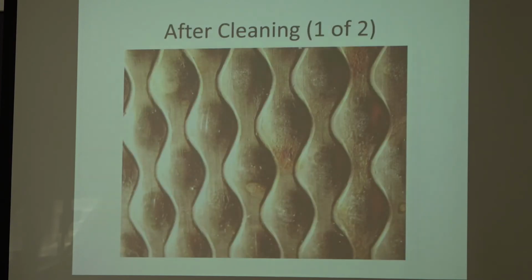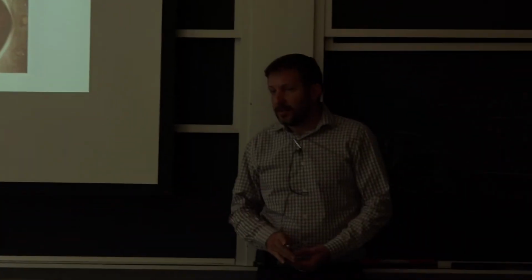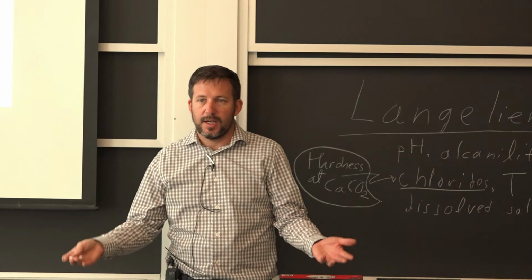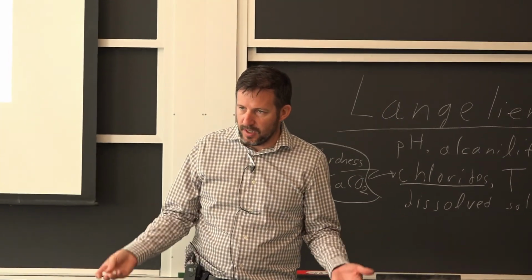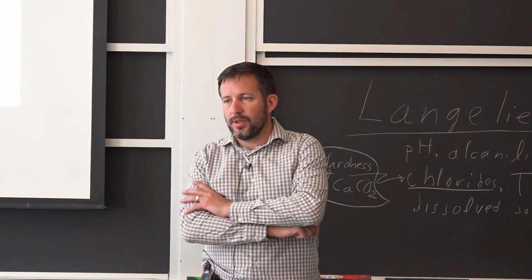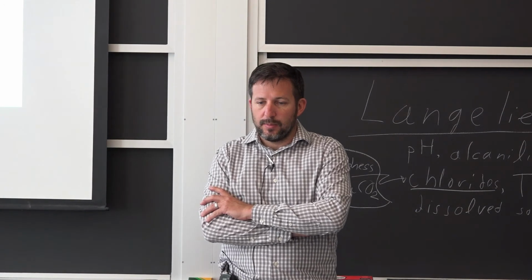So what happened? They used an acid cleaner. This is like the pickup and drop-off area. They used a big acid cleaner because they were just finishing the tiles. And it wasn't windy that day, so there's essentially been a very acidic environment staying in that region to cause the problem.